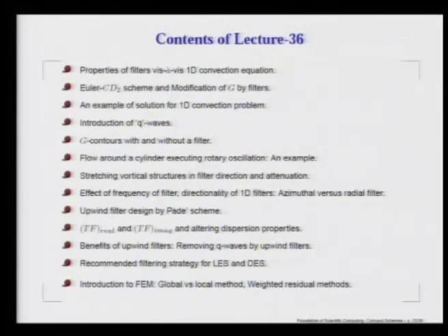Now, in the following, we discuss a new class of filters that we have designed, where the filters themselves are upwinded in the interior. Once again, this is done using Padé schemes, and we work out the transfer function real and imaginary parts and identify the alteration of the dispersion properties.